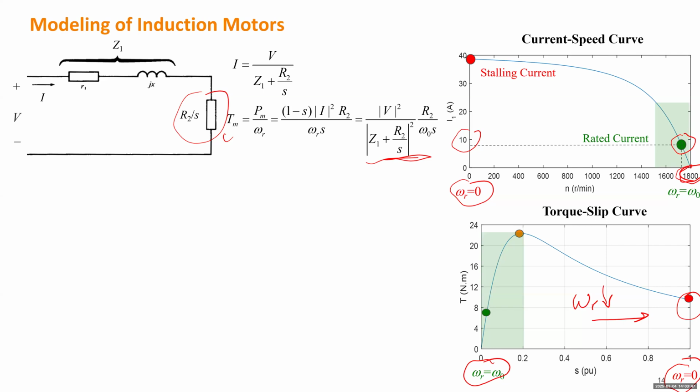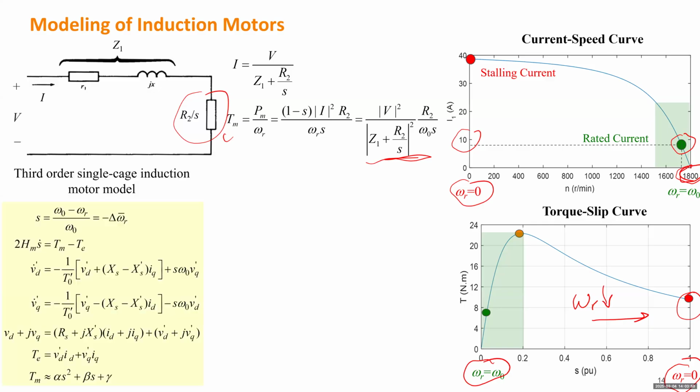Because the mechanical power is equal to the product of the torque and speed, even if the torque is non-zero, speed is 0. It doesn't consume much energy based on the formula. So those equations just give you some characteristics based on the circuit, but if we want to model dynamics, because it is a dynamic load, those equations don't give you dynamics. We need to introduce differential equations.